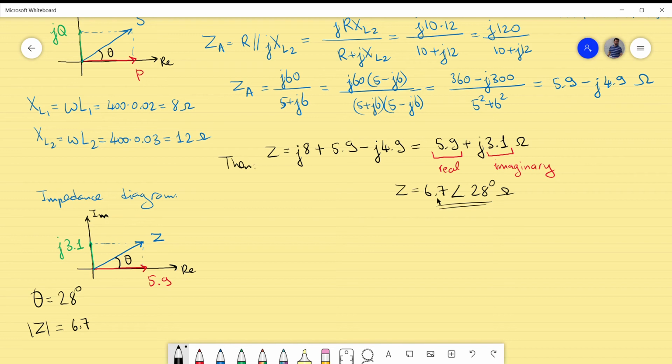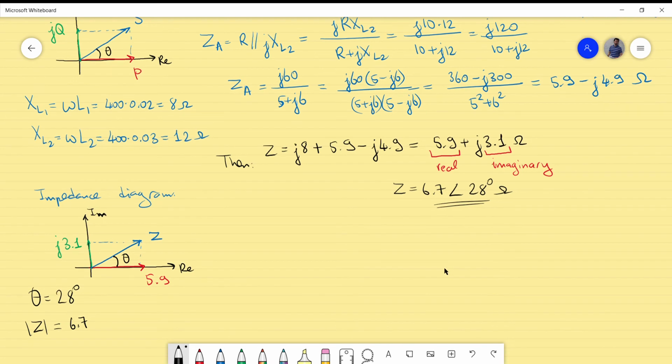That's actually the whole issue about the total impedance. Now we require the total impedance. Why? Because we will also like to go to the total current supplied by the voltage source. So the total current by the voltage source, IS, in RMS, of course, that is required to calculate the powers, is equal to the V source in RMS divided by the total impedance seen by the source.